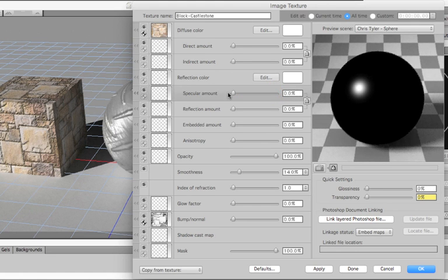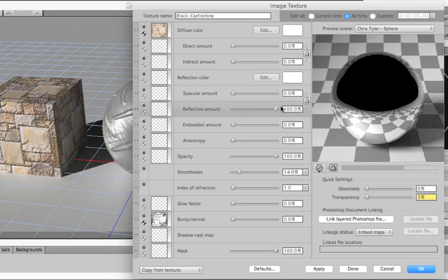You can see that in this preview model, there's not a lot to reflect beyond the checkerboard floor. The sky is black, and there is no reflective background assigned to the preview model. It's important to remember when you create a new model in Design 3D that if you choose the New Empty Model option, it will be just that, an empty model. So if you place an object in the model and give it a reflective texture, it won't seem to be reflective because there will be nothing in the model to reflect.